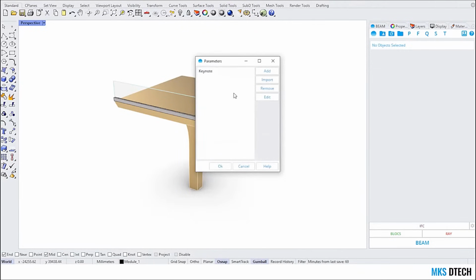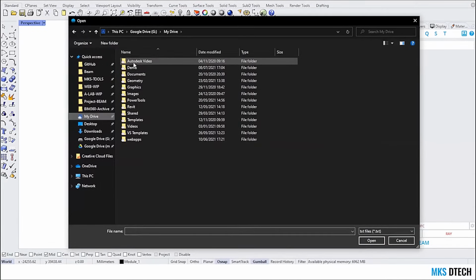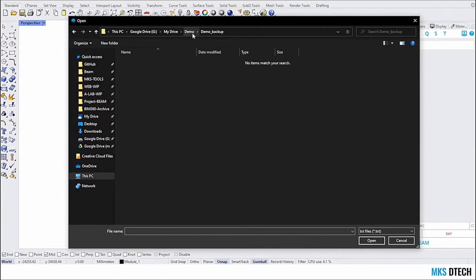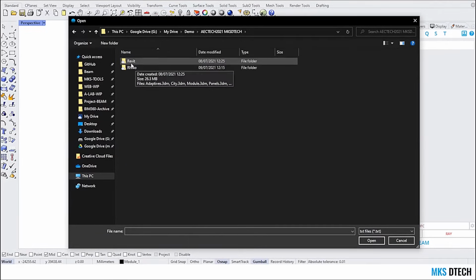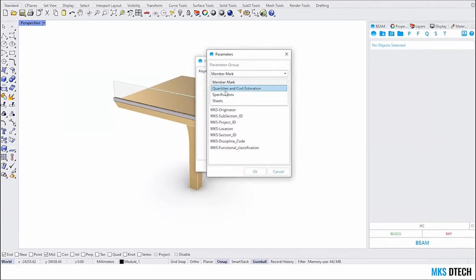On a later date, I can even import from a shared parameter file. So I'm gonna do it now. We have put in your folder a shared parameter file, which should be in the Revit folder. If I open it, I will have this interface where I can select a group and pick a parameter I want, for example, MKS units.